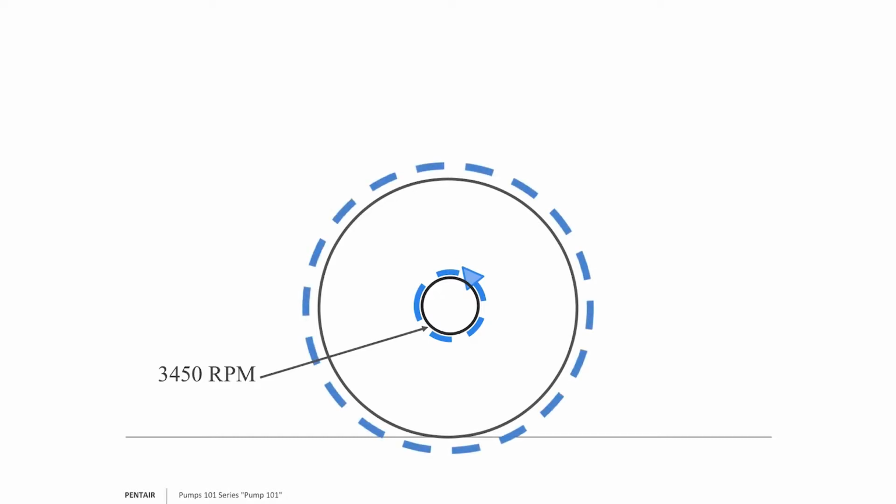Now, which direction is it going to spin? Well, it's a solid object. Of course, it's going to spin the same direction as the eye of the impeller, counterclockwise, okay? But now, what RPM would it spin? Well, it's going to spin the same RPM as the eye of the impeller because it's a solid object. I'm not trying to make you feel dumb or pick on you here or ask you trick questions. I want you to understand we're talking single speed here, okay? When you're talking a single speed, the outer peripheral will spin at 3450, the same as the inner peripheral.